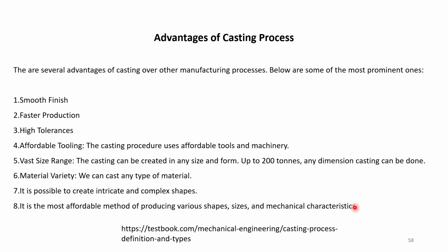Okay, so there are several advantages of casting process. You'll be getting smooth finish in die casting and other castings. You'll be getting very smooth finish. In sand casting, you'll be requiring some finishing, yet you find some smooth finish. Next, you have faster production, and you have high tolerances, and you have affordable tooling.